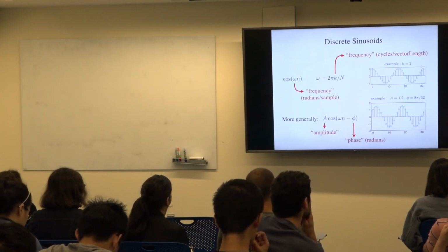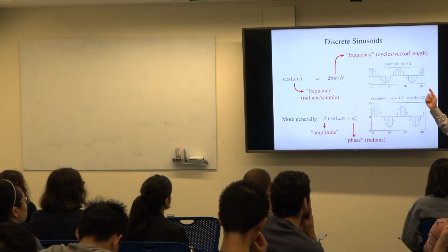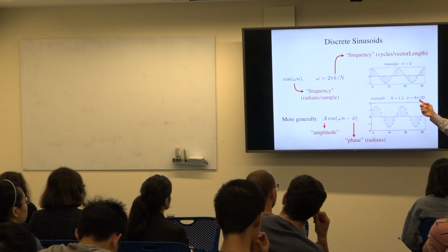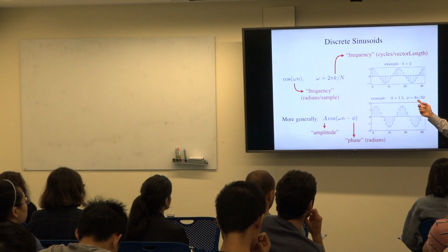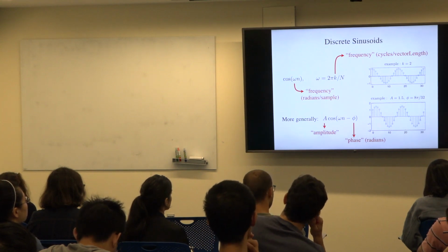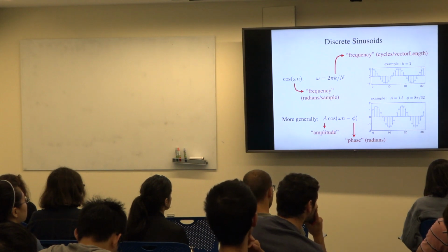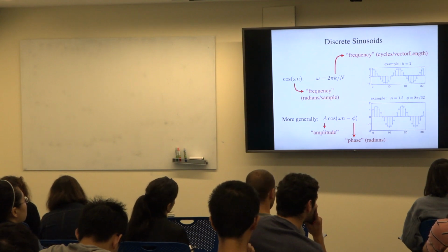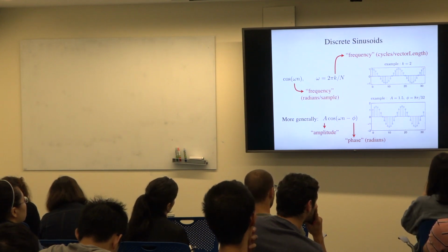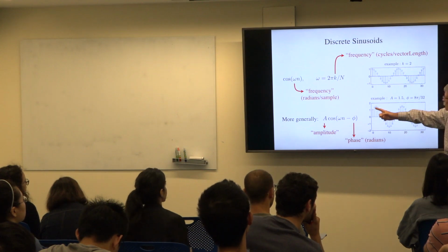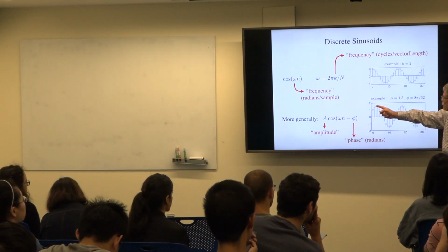But another way to think about it is 2 pi used to be 32 samples, right? 2 pi is the whole signal. And I'm shifting by a quarter of pi, which is an eighth of 2 pi. 2 pi was 32, oh, wait, did I just do the arithmetic wrong? I did. Where did I screw up? Hold on a second. A quarter of pi is 1/8. Is the picture wrong? Maybe the picture's wrong. When I looked at it last night, I thought the picture was right. But you look at the picture, this picture has been delayed in time. And it's been delayed in time by 2 samples. Here's the extra 2 samples, because this sample used to be at time 0. It's been shifted over 2 samples.